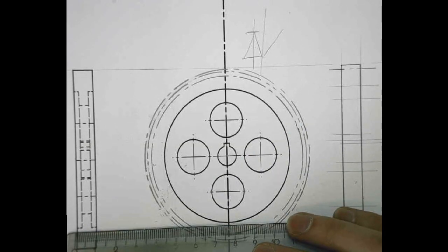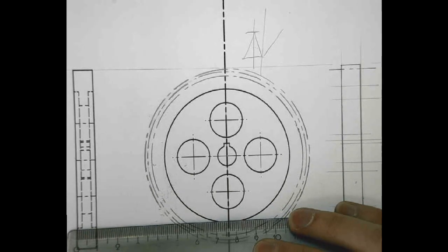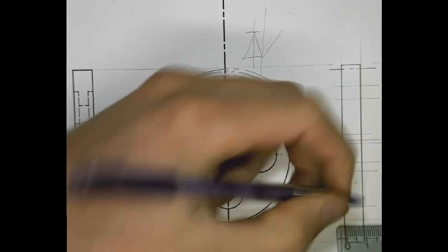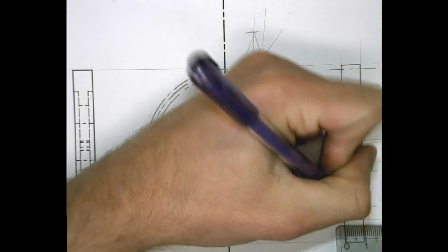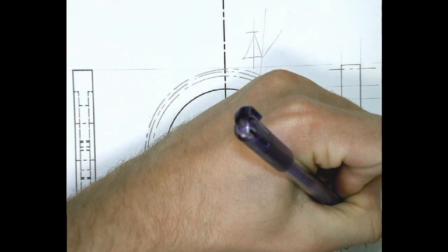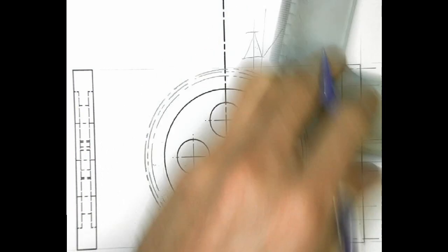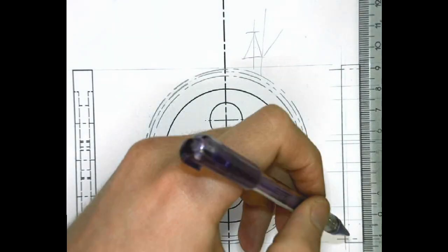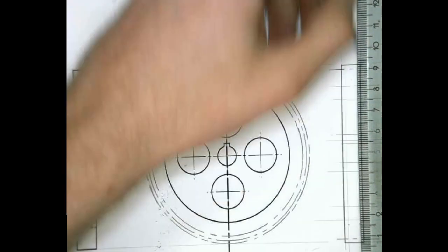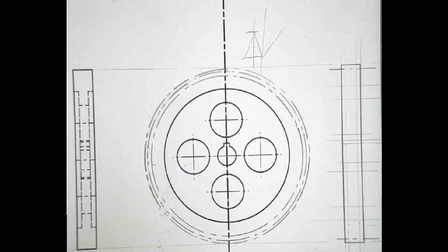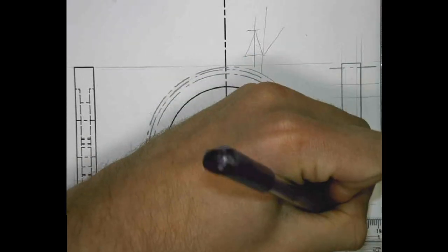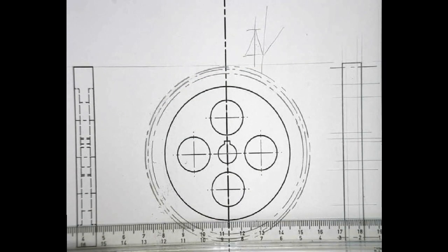We'll then measure the width of that recess of our side view, and it's 2 millimeters. So we can mark off 2 millimeters from there as well as 2 millimeters from that side. I'm going to put a construction line straight up on either side and then fill in the detail for that recess on either side.